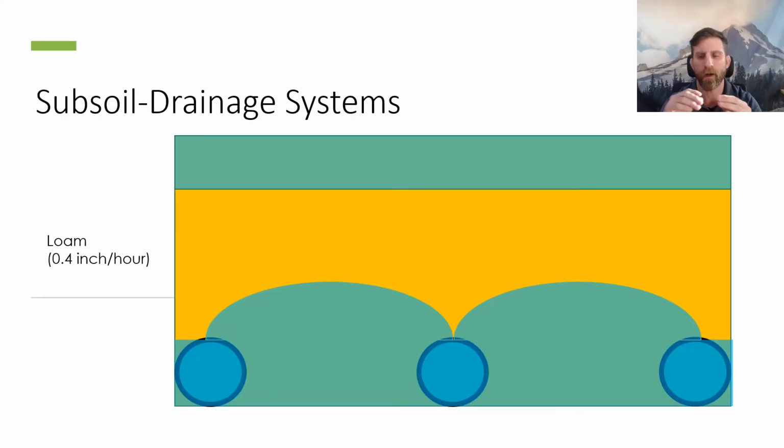So in our previous lecture, we talked about subsoil drainage systems. And remember, in our subsoil drainage systems, we're putting drain tiles down in the subsoil to control the water table. So if we put drain tiles down in the subsoil, we have these drain tiles move water to low-lying areas. We can then decrease the water table and stop the soil from saturating up from the bottom here.